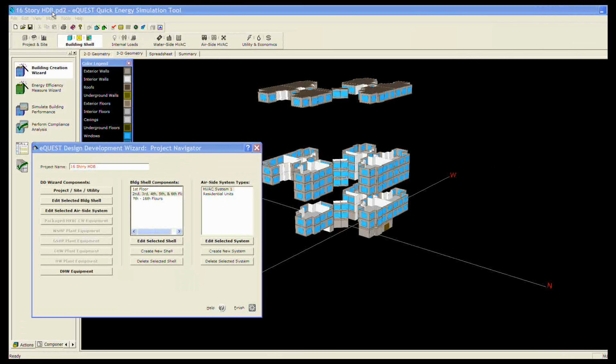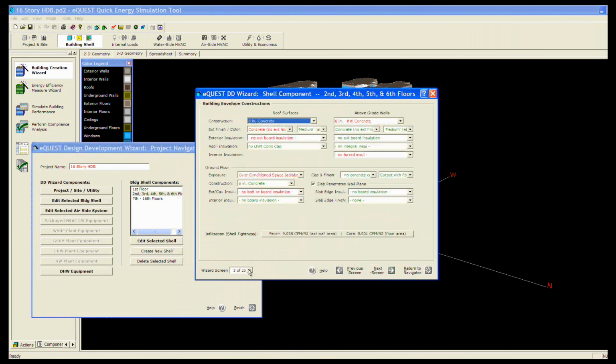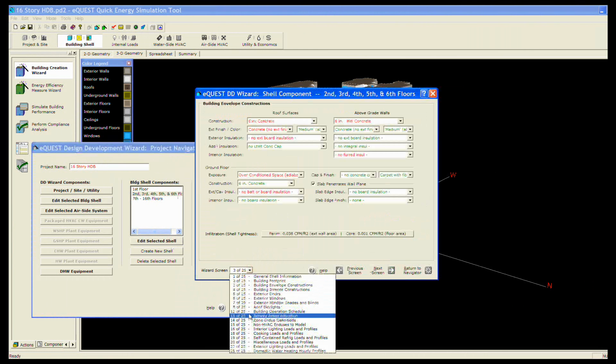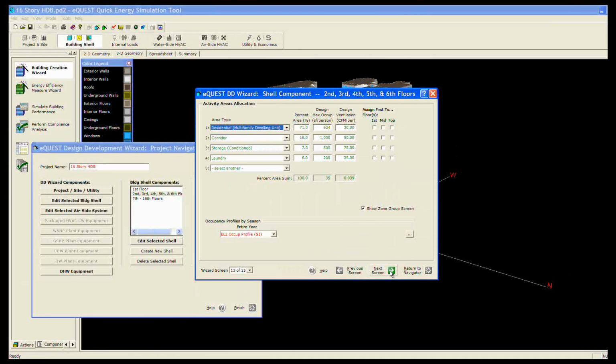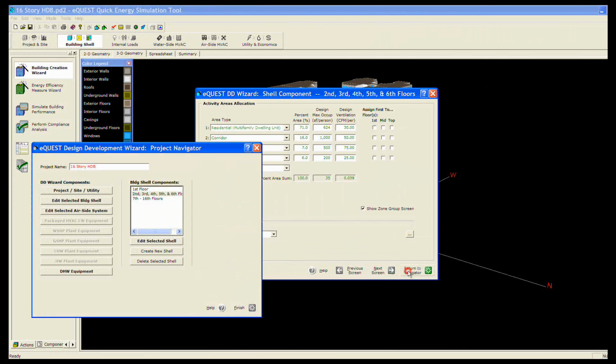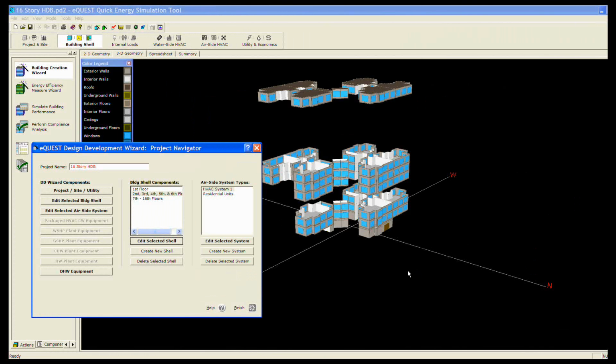After defining the urban form in GIS, the generic building and land use types will be simulated in a building energy performance software called eQuest. By inputting the detailed parameters on envelope design, schedule of operation, area usage, and other building performance parameters for each type of building and land use, the tool is able to generate hourly energy demand of these generic building and land use types, which will be later imported to the system dynamics simulation engine as energy demand.